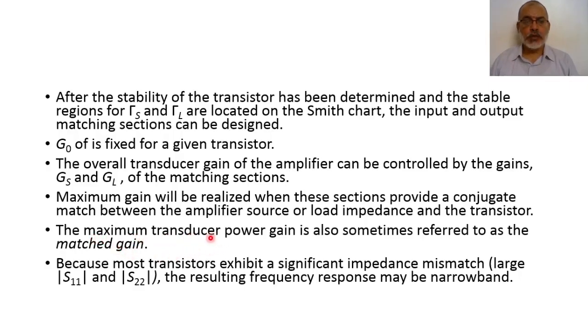The maximum transducer power gain is also sometimes referred to as the matched gain because the maximum transducer power gain is obtained when both the load and the source are matched to the transistor from the output and the input of the transistor.